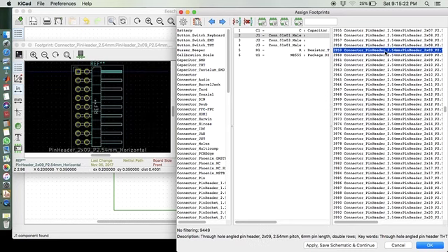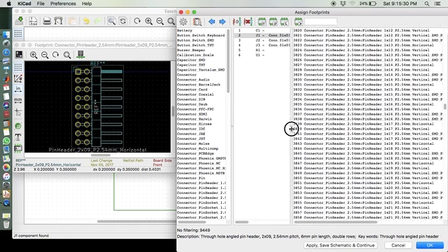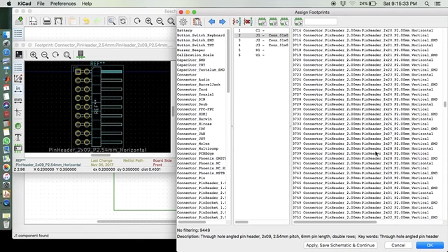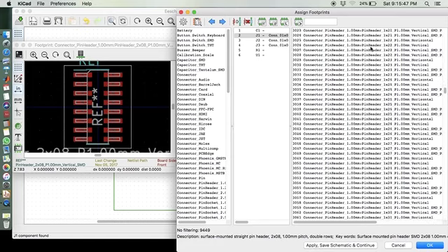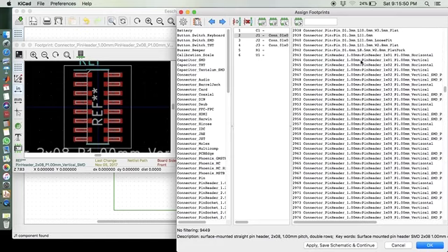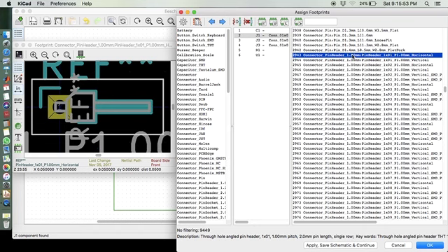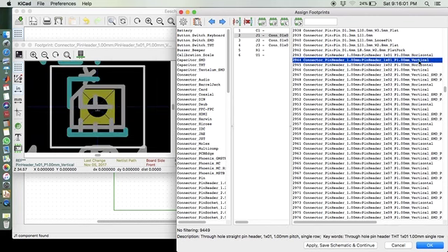These are multiple pin header connectors. Let's choose a single pin header connector. The number of pins is written here. These are 8 pins. Pin header, the first one we can choose under this list. Not this. So this is okay, this is the right connector we need. Single pin connector is this, but this is horizontally aligned. We need a vertical connector, so we'll choose this.